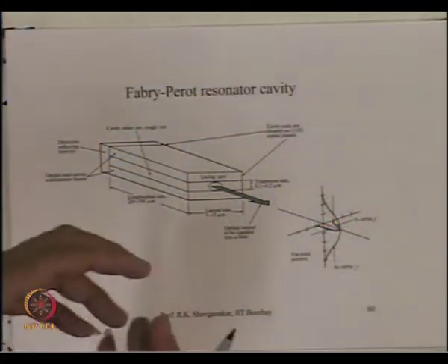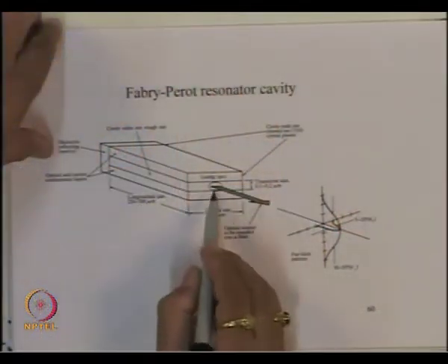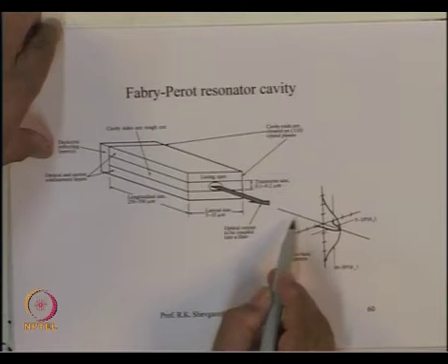Nevertheless, the angular width which you will get from this device will be much smaller compared to LED. So, you typically get a few degrees cone from this device, whereas as you remember, the angular cone over which the power was coming from LED used to be essentially 180 degrees. So, the laser diode essentially gives you a beam which is reasonably narrow.